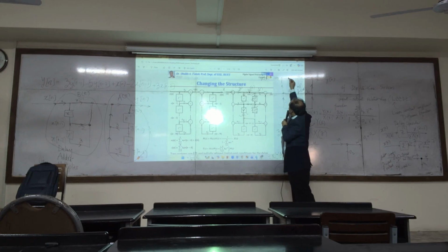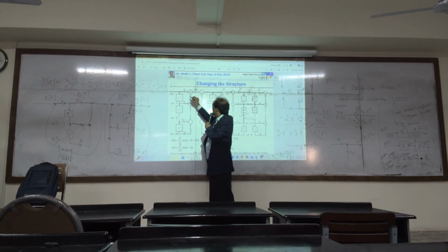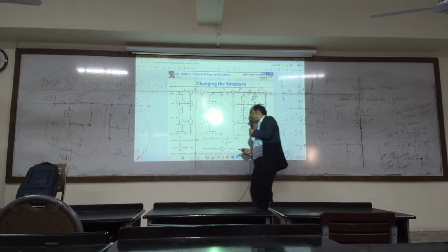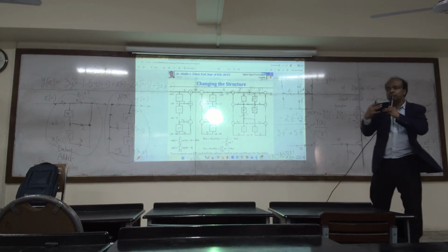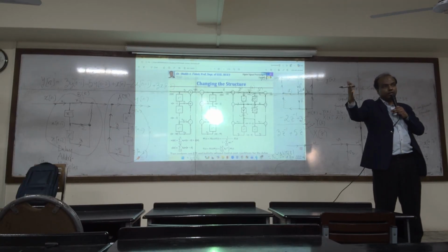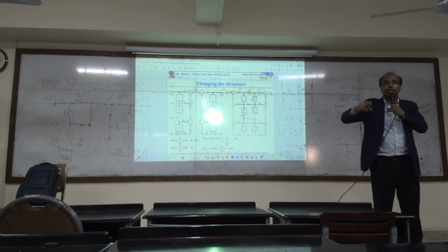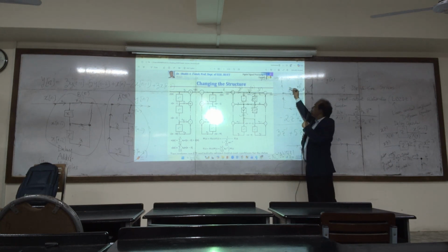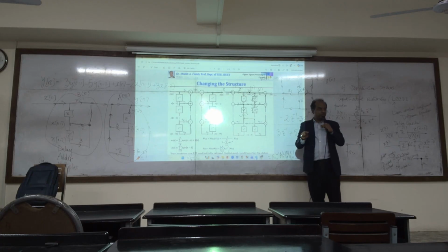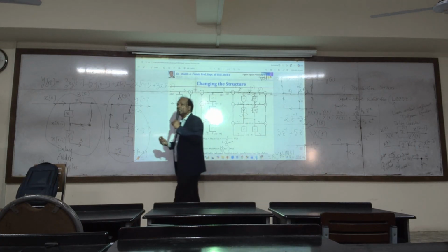1 input, 1 input, 2 input, 1 output. Here they have written it very nicely. But when you draw a signal flow graph, you don't have to explicitly write it. People will understand: when 2 input, 1 output, adder. 1 input, 2 output, not an adder. If you have to do A minus B or something, don't put a minus there. That is an add. If you want to do subtraction, just make the coefficient negative. That's it.